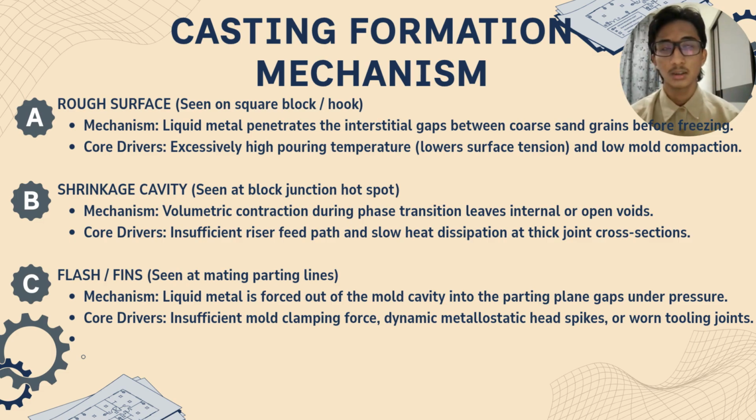The reason can also be an insufficient riser feed path and slow heat dissipation at the thick joint cross section. When you don't have a riser feed, there's no extra molten metal available, so the product will not be fully filled with molten metal. And last but not least, flash fins.